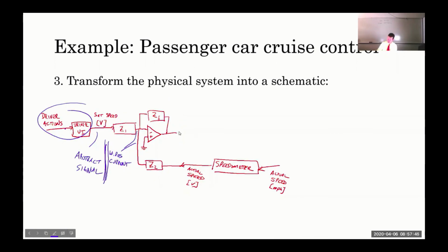Oh no, what have I done? Okay, sweet. Okay, so I want you to see that this network, this Z1, Z2, ZF, and op amp will perform filtering. It will also perform summing. It will also perform amplification, if we like. I think that what we've just done is we've modeled the controller as a summing op amp.